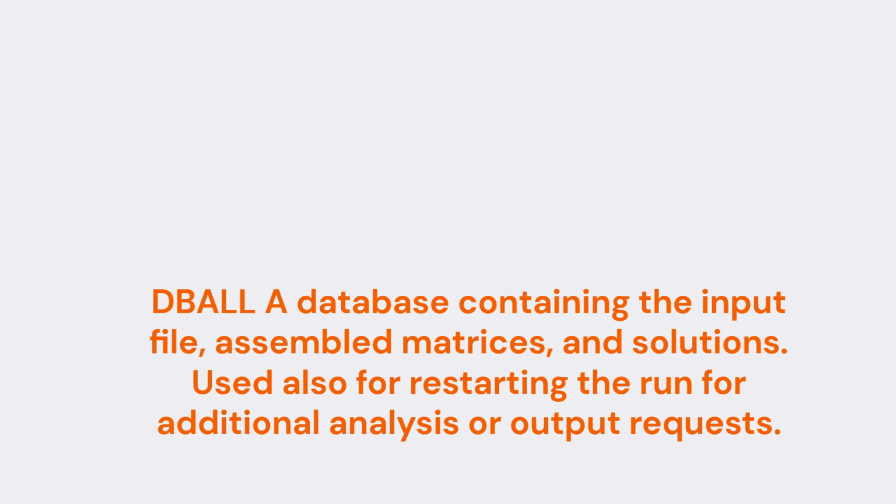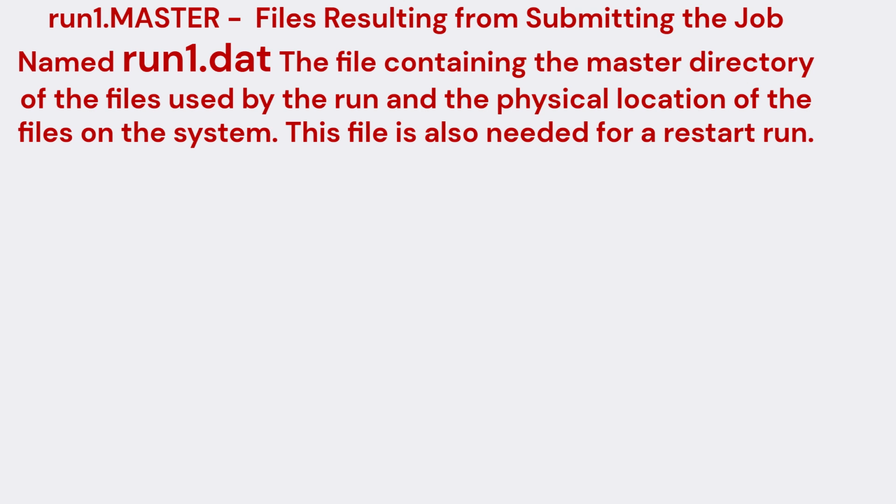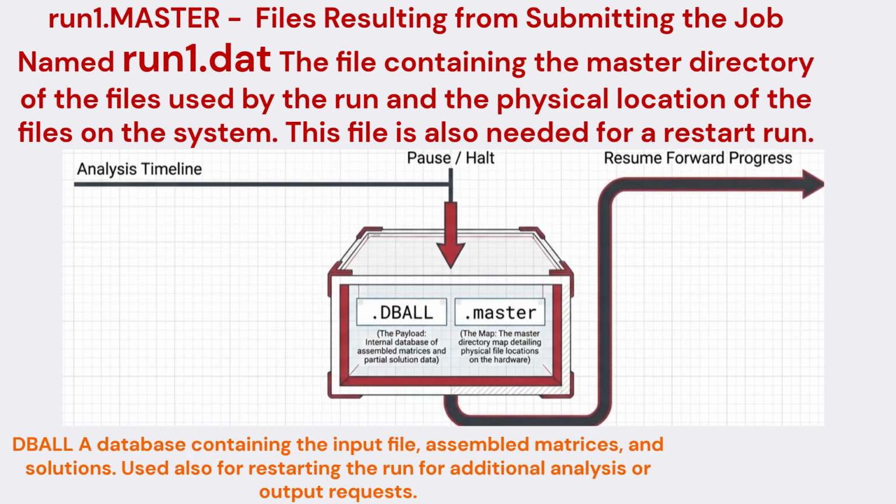Next is the master file. This file contains information about the master directory and the files used during the Nastran run, including their physical locations on the system. The master file is also important when performing a restart analysis.